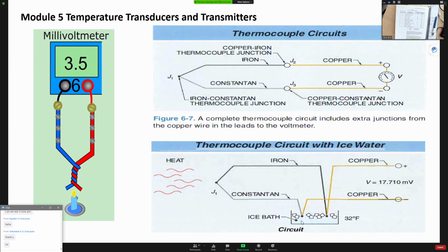It's because if you have pure ice, the temperature could be below 0 degrees. Here it gives you 32 degrees Fahrenheit, which is actually 0 degrees Celsius. If you only have water, the temperature could be above 0 degrees. Only when there's a mixture of ice and water together is the temperature at 0 degrees. So that's where this measurement will be more accurate, if you put the reference junction into this ice and water combination.